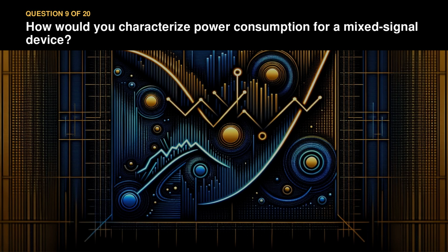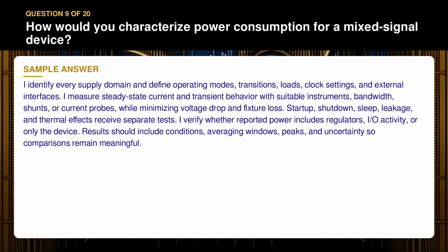Question 9. How would you characterize power consumption for a mixed signal device? I identify every supply domain and define operating modes, transitions, loads, clock settings, and external interfaces. I measure steady-state current and transient behavior with suitable instruments, bandwidth, shunts, or current probes, while minimizing voltage drop and fixture loss. Startup, shutdown, sleep, leakage, and thermal effects receive separate tests.